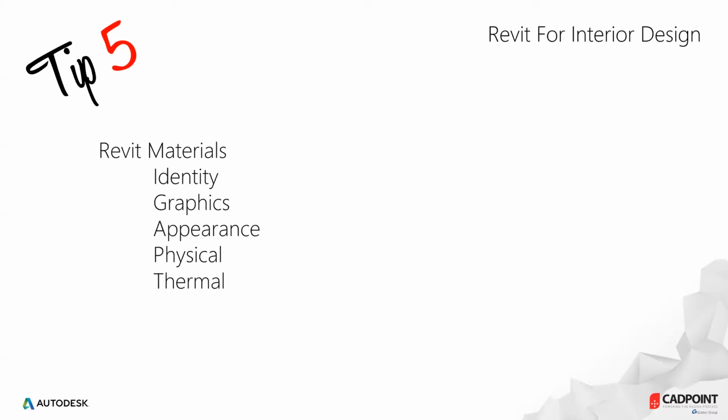You could have different materials, so names that share the same render appearance, but have different identity and graphical characteristics. An example could be a grey matte paint render asset. It can be shared between a skirting material and an architrave material. So they're both going to appear as the same grey paint, but in Revit, one is a skirting and one is an architrave. So let's go and have a little look at that.